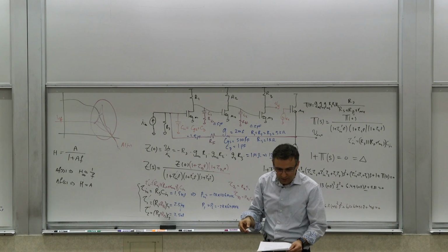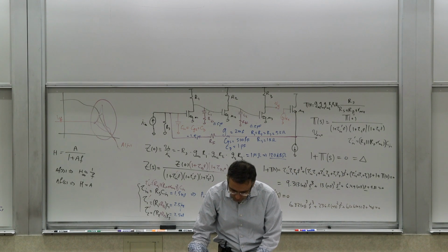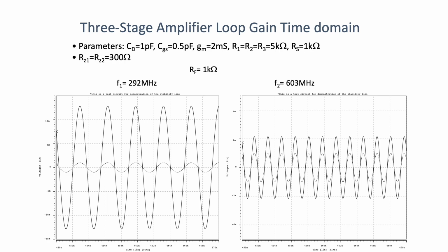And if you want to see this more explicitly, you can see that at these 2 frequencies, we actually opened the loop and applied that signal. This is very important, actually. So look at these 2. The output is larger than the input, and it's completely in phase with it in both of these cases, because you have 180 for the loop gain, and there's a minus sign in the loop gain definition, so it's like 360. So the signal's going in, it's coming back exactly in phase, and it's larger than what went in. Vy is greater than Vx, and it's exactly in phase.